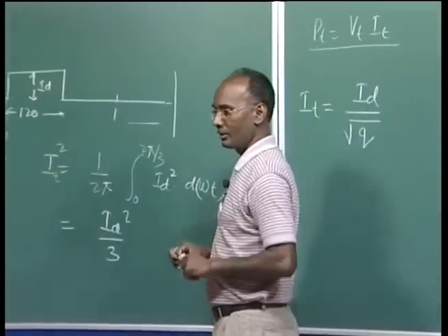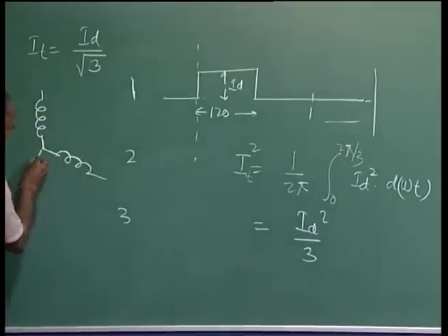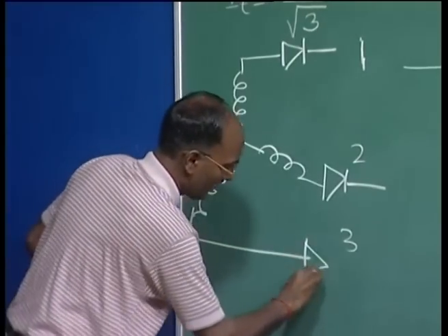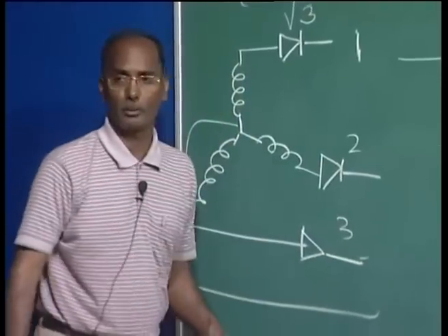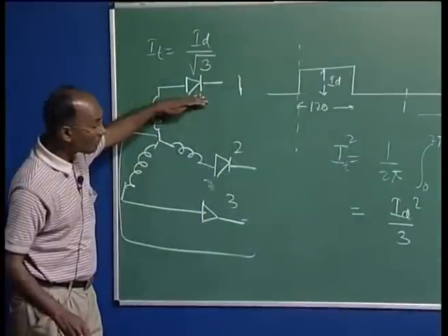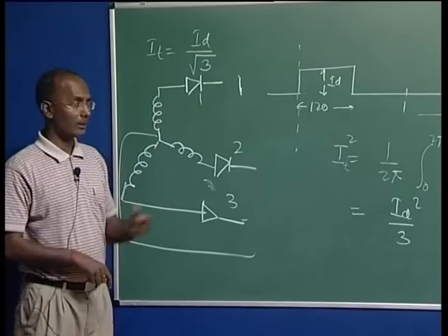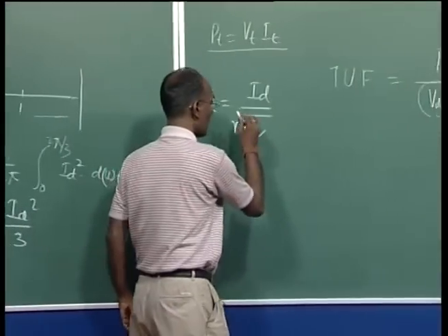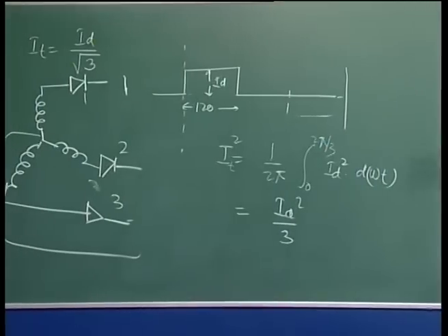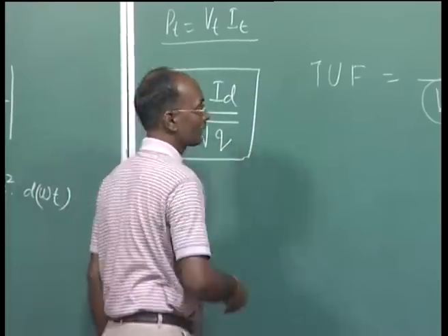Now, if the valves are in parallel, here this configuration is nothing but the windings, these 3 windings, and we assume we have valve 1 here, another valve here, another valve here, and the neutral as a return path, if you remember. So, this is valve 1, 2, already written here. In this case there is only one valve in series. There is a possibility you can have 2 valves in parallel. Then that value will appear here with R. R is the number of parallel valves connected with the winding. So, this IT is your general term, this expression that we have to use.